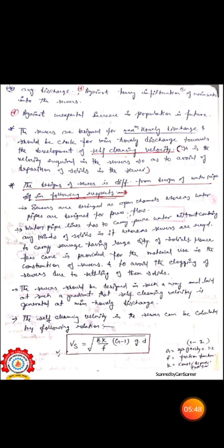We need a self cleaning velocity in the sewer. Why is the self cleaning velocity required? Because the velocity is required in the sewer so as to avoid deposition of solids in the sewer.